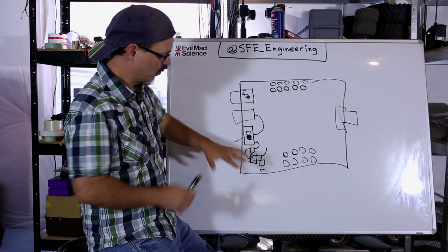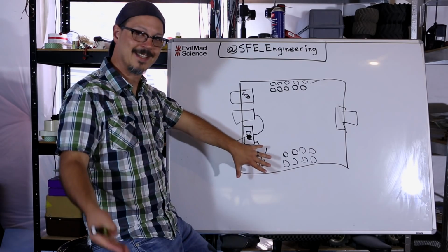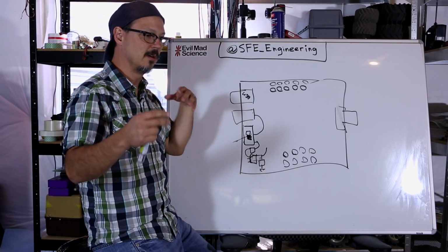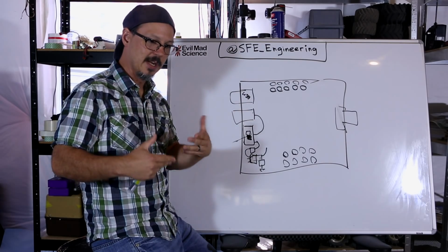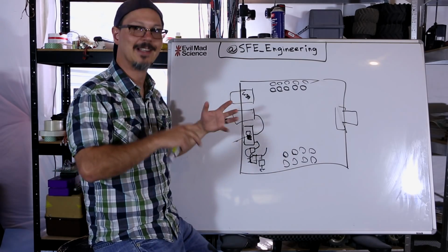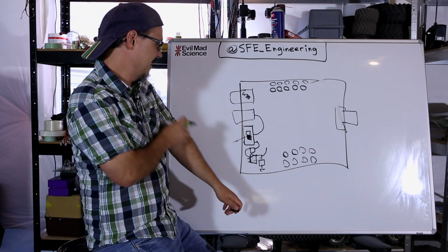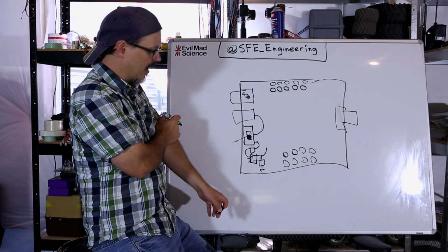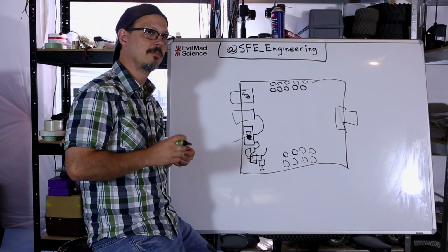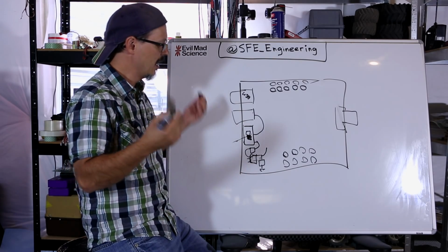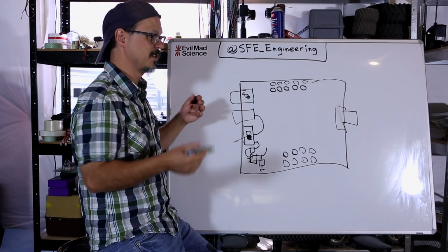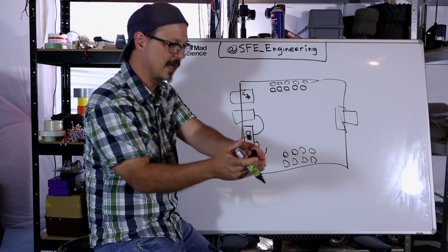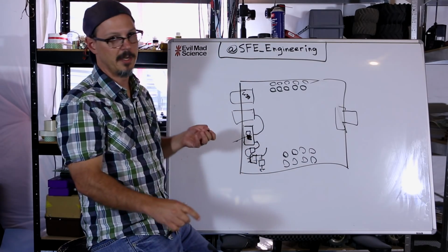And like I say, you want to do this according to what the schematic shows. You want components that are close electrically in the schematic to be close physically on the board. How do you feed these things? Generally, when I do it, I will do a modified star configuration. And a star configuration is just that each section gets its own dedicated line back to the regulator, right?